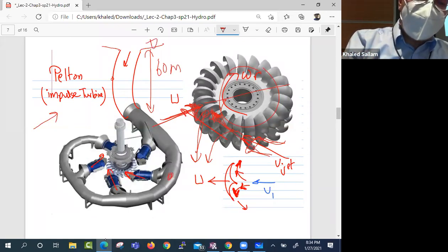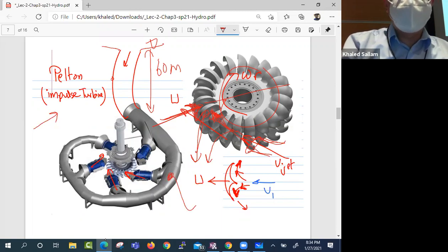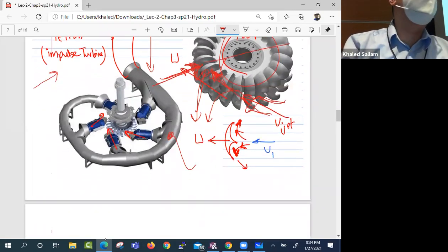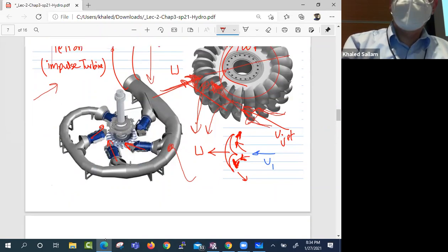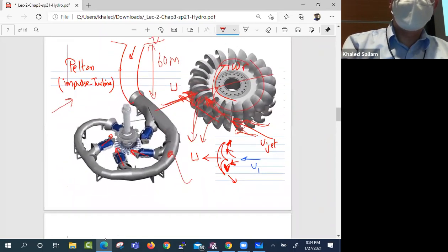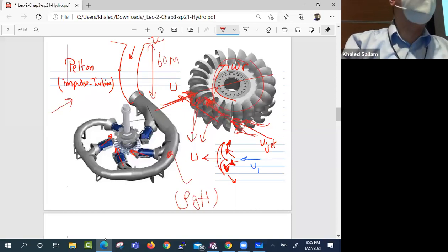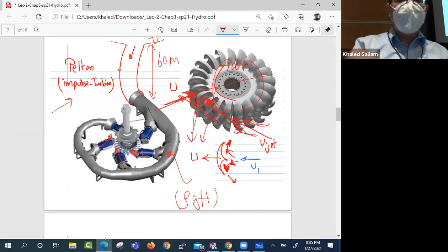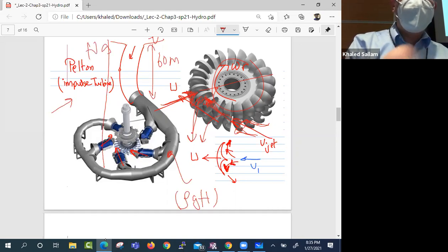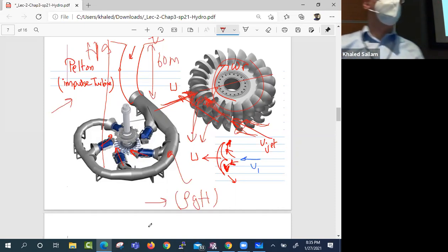By the time it hits this point, what is the pressure here? Maximum, like what's the ideal pressure? Assuming no losses in the pipe. Ideal pressure would be rho g H. If it's not moving, if nothing is converted to kinetic energy, all the H that you have on top of you, the hydrostatic pressure, basically, that's the rho g H. Right?